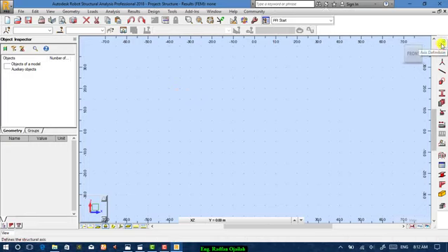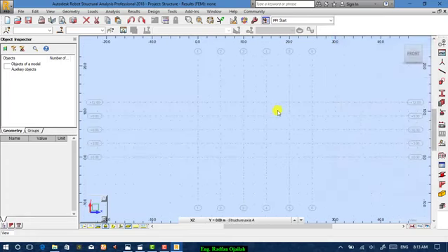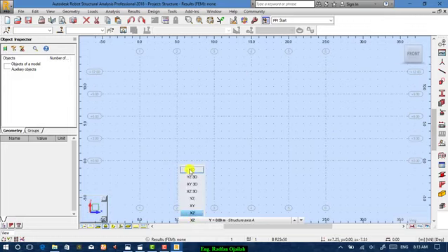So go to our first step, which is axis definition, by defining the grid. For example, for x-axis we have 5 by 5, and for y we have 5 by 4, and for z-axis we have 4 by 3. Apply. And to move to the 3D, go from here.